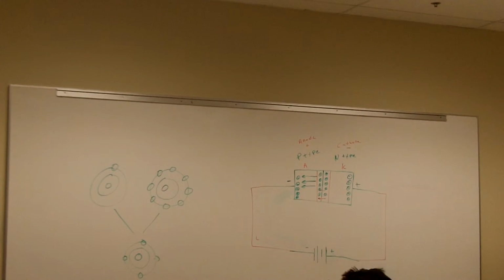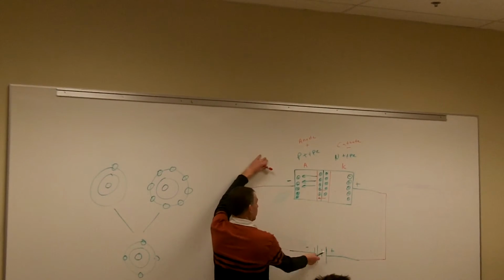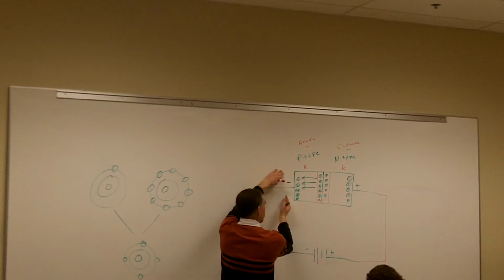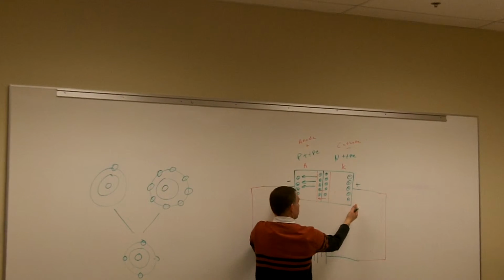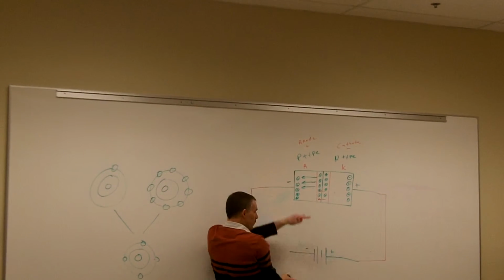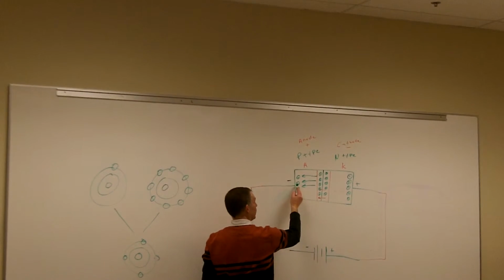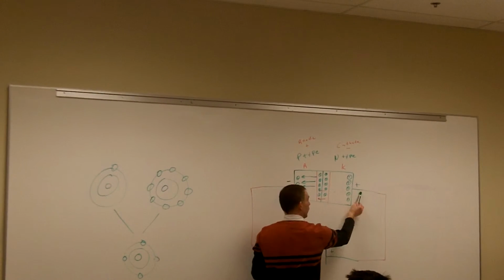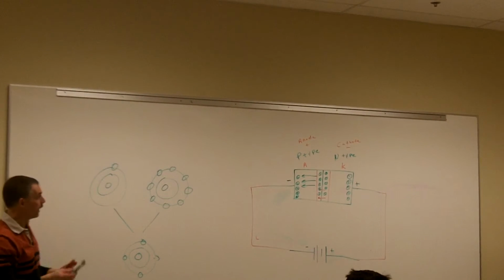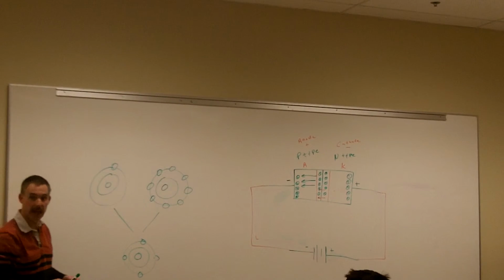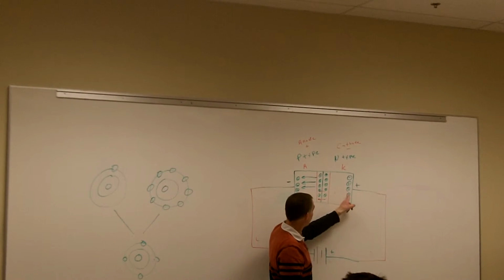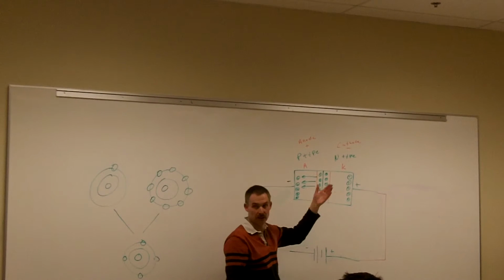But if we apply enough voltage, so let's say right now we're in a reverse biasing. My depletion area is really large. I'm more negative on this side, more positive on this side, so I'm in reverse biasing and the current's not flowing. But if I crank up my voltage so much, I can overcome this barrier potential and start getting these electrons flowing through that semiconductor. That's still reverse biasing, but it's in a breakdown mode. We're actually breaking down that diode, forcing those electrons so hard across that barrier potential that we're damaging the diode, and it'll end up burning out.